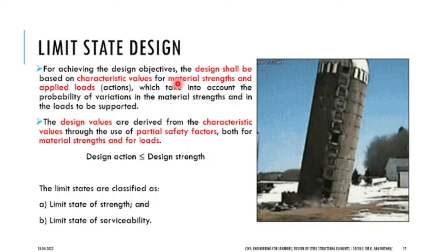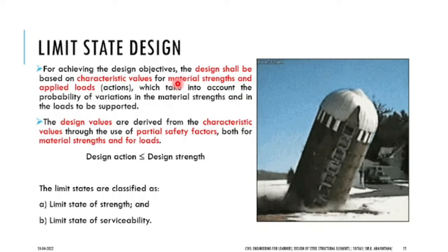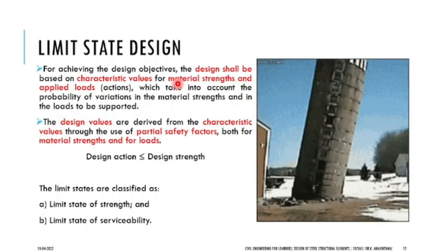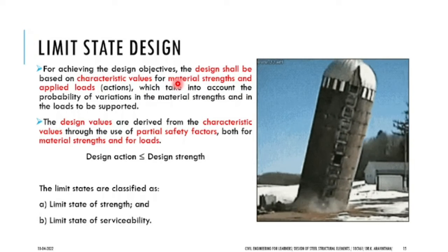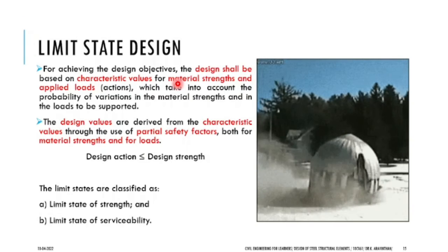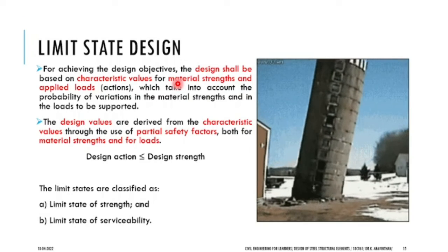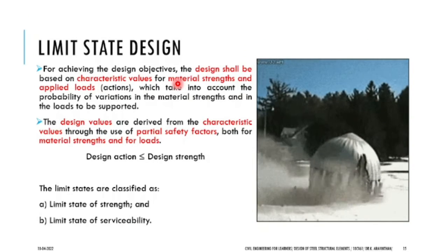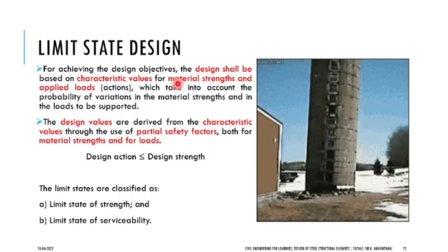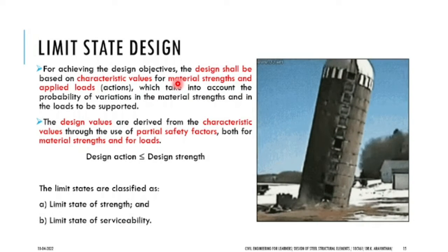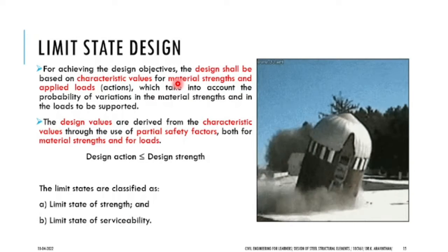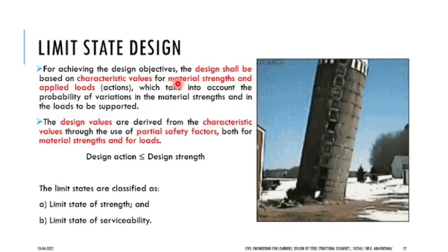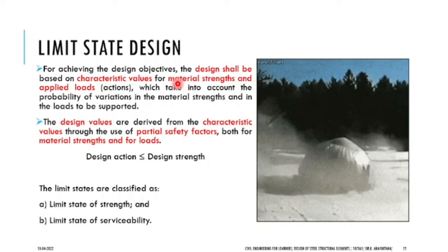If you are manufacturing 100 products, say for example toys, 100 toys are being generated. Can we say that 100 toys are of the same quality? There will be some defects. Even in a toy factory, you might see the same doll, but different qualities. Around 80 to 90% similarity you can expect. The same way, if they are giving Fe 230 grade steel, you should not take 230. How much should you take? Only 80% of the strength you should take.